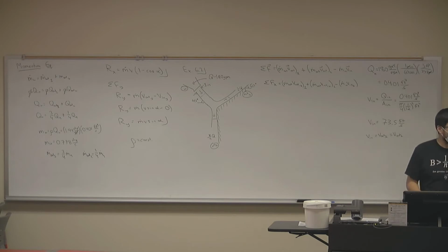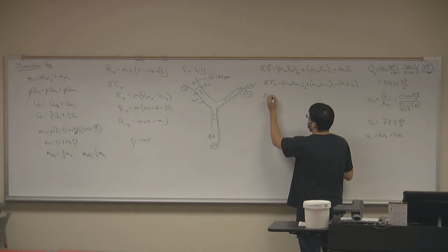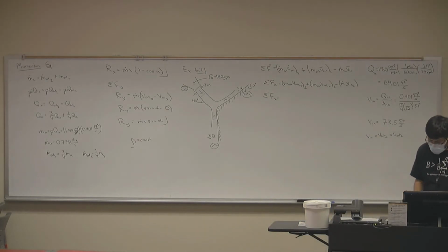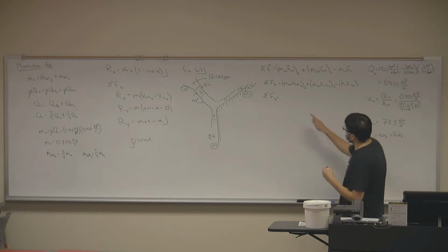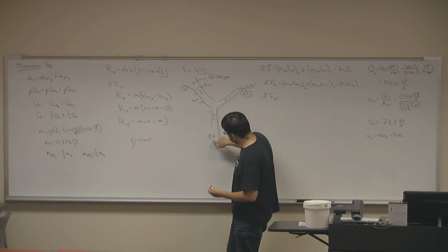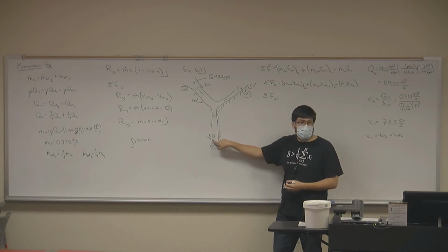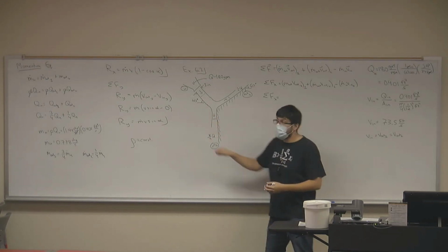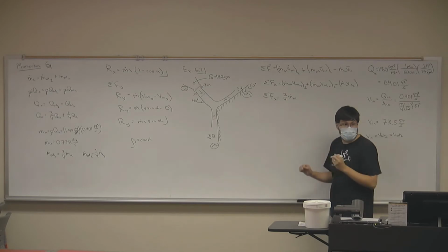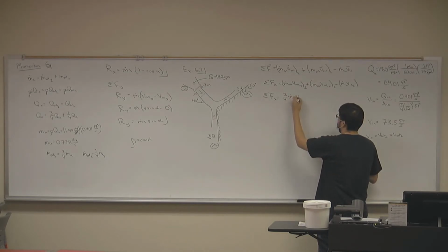Does that make sense? If it doesn't, let's just go ahead and write it on the board. So we get that sum of forces in the x direction equals what? Well, in the x direction equals mass flux out for my first outlet. But we know that for the first outlet, the mass flux is only 3/4 of whatever was coming in, right? So I can write this instead as 3/4 of my mass flux in, times the x component of V out.